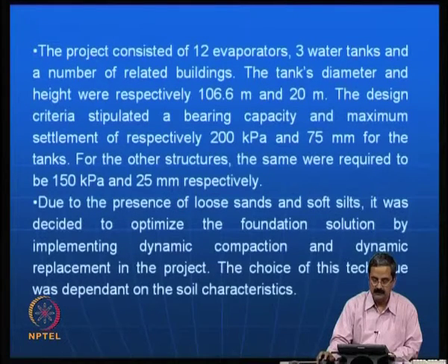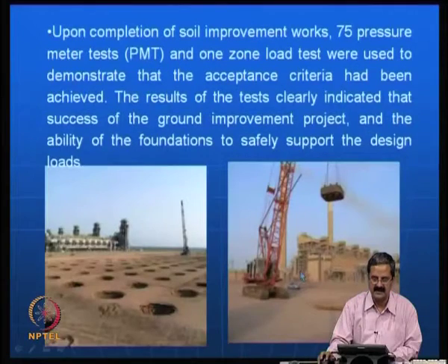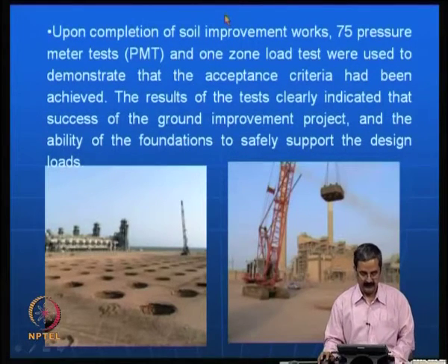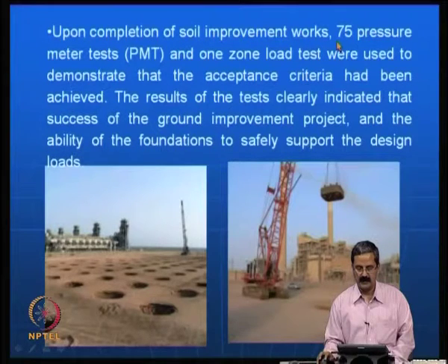Because of the presence of loose sands and soft silts, it was decided to optimize the foundation solution by implementing dynamic compaction and dynamic replacement in the project. The choice of this technique was dependent on the soil characteristics. Upon completion of the soil improvement work, this is the type of work that they undertook. This is from the particular company. They did 75 pressure meter tests and load tests to demonstrate that the acceptance criteria had been achieved.